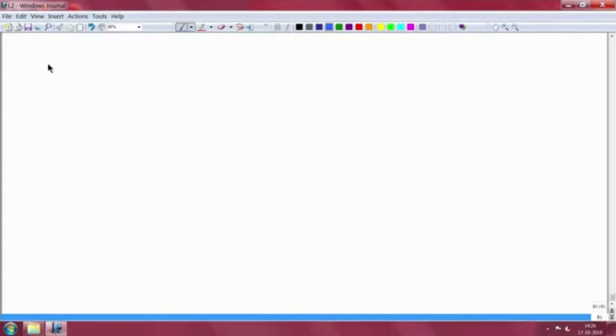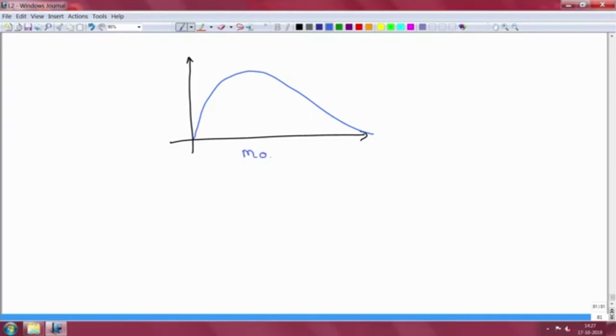Okay. So, in a normal situation you might have a very large distribution. Sometimes when we source these polymers from an industrial source, what we end up getting is not a set of molecular weights, but an entire curve of molecular distributions. So, let us say this axis is molecular weight, and on this you have the amount of polymer.